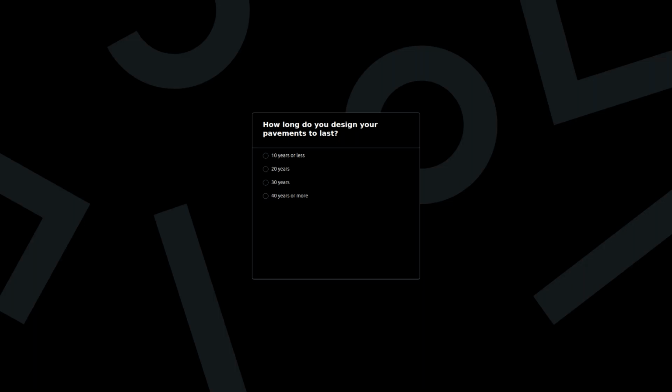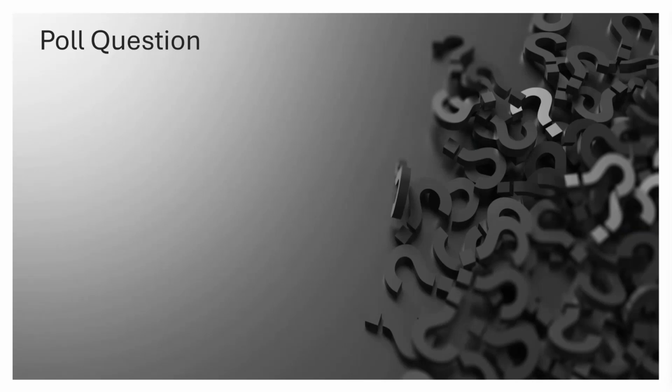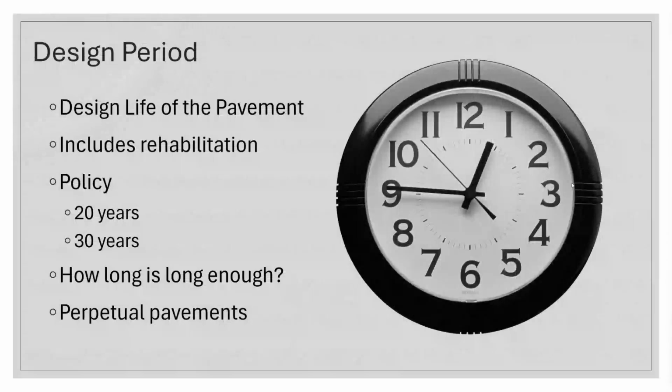All right, the most popular answer, about 2/3 of you put 20 years, and we had some that said 10, some that said 30, and just a few said 40 years or more. I would love it if they lasted 40 years or more. But the design period is how long do we want that pavement to last? And that doesn't mean how long will that asphalt surface last. That means how long do we want this structure to really carry us forward.